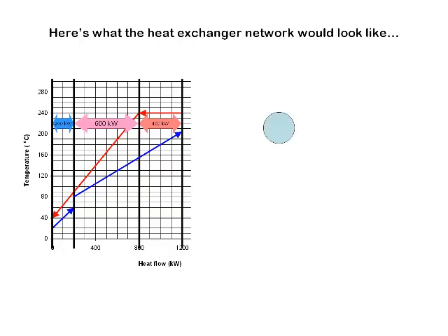Okay, let's try to make this a bit more real by thinking what the heat exchanger network would actually look like for this system that we've put together. So here's our heat recovery heat exchanger. This is our middle heat exchanger. It's got the cold stream coming in at 80 degrees Celsius, and we remember our cold stream had a flowing heat capacity of 8 kilowatts per Kelvin.